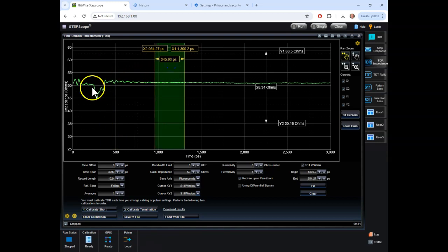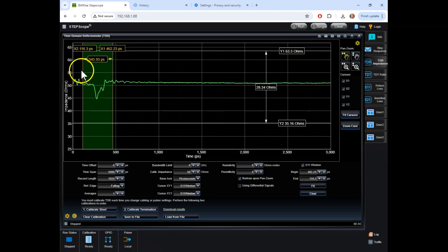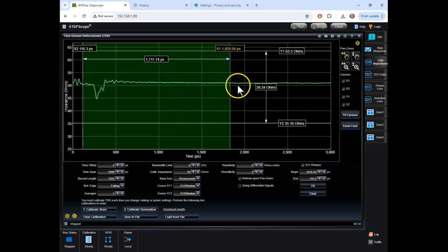Now, what I'm interested in is not the leading edge where I have my cables and connections or the PCB trace. I'm really interested in getting into the chip. So I'm going to set this after the connector to the starting point and set the ending point somewhere down farther, so that I'm basically going to ignore getting onto the test structure through the SMA connectors there. It will set my time for the beginning and ending so that I have the window.